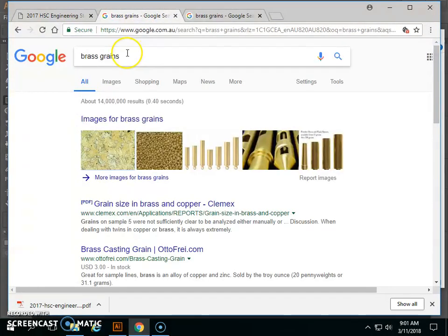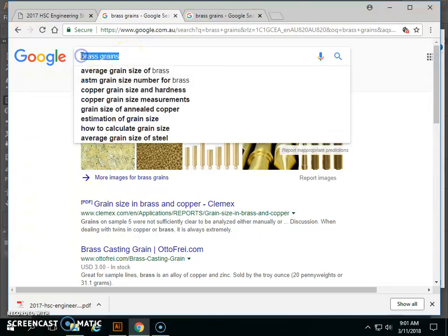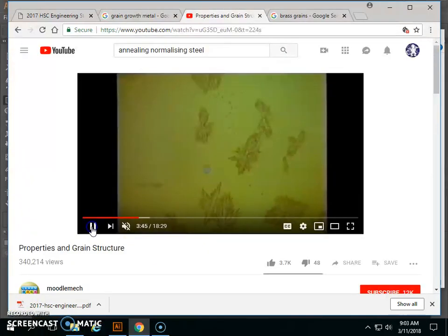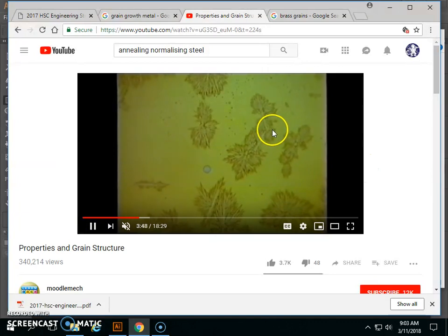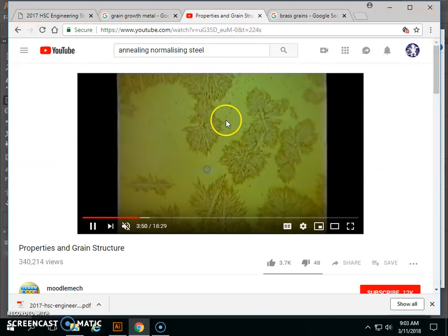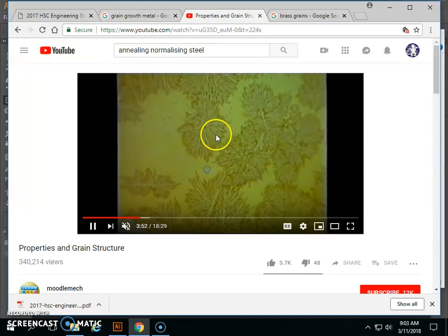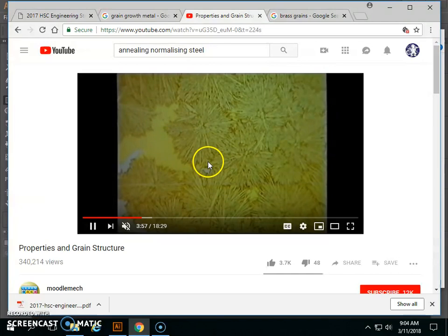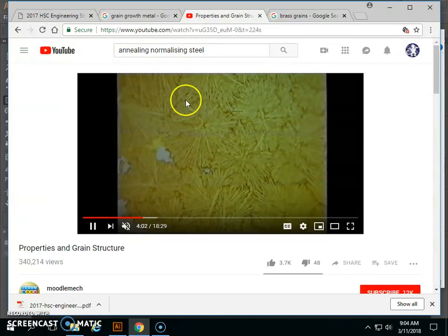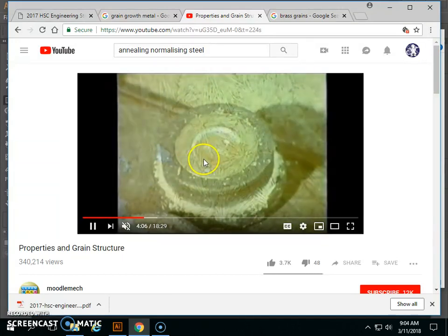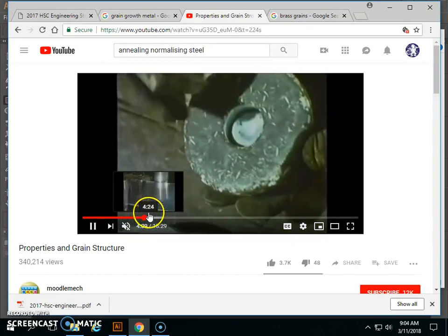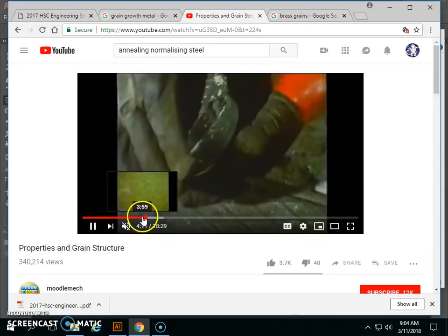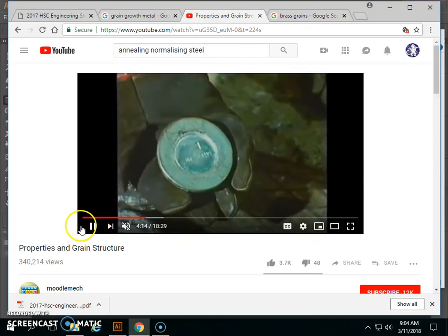Well, it means little trees, but so if we talk about grain growth, one second. Okay, this stuff here, that's called dendrites. So we start off with nucleation points. The nucleation points, the little dots, grow into little trees or dendrites. And then eventually when they start to meet, we form grain boundaries. So when we draw a picture, these are equiaxed grain boundaries, because even though they're not circles or squares, they're not favoring a direction. They're not favoring the x-axis or the y-axis. Okay.